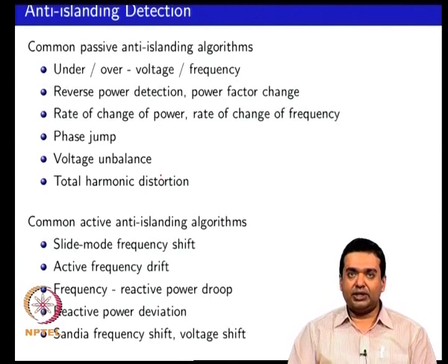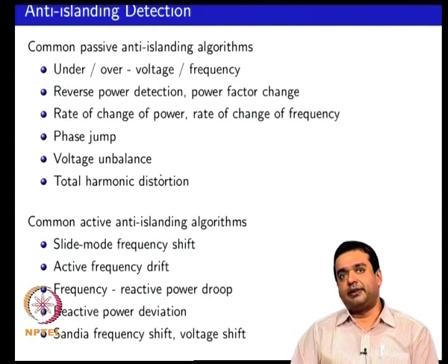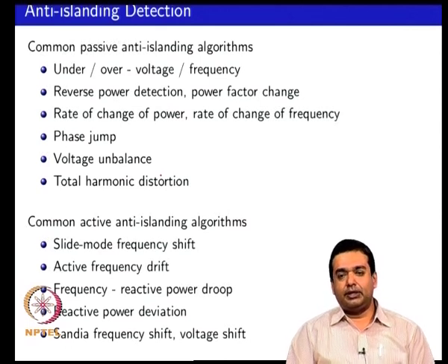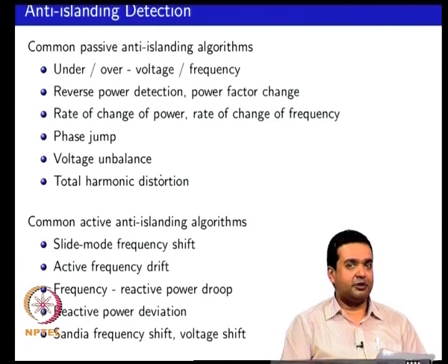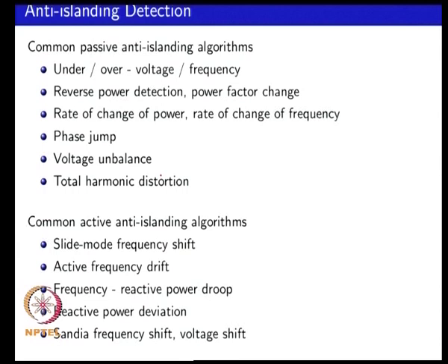People have looked at other methods such as power factor change, rate of change of power, rate of change of frequency, whether there is a sudden phase jump in your system, whether there is a large imbalance happening in terms of the voltage, whether there is an increase in THD that is being measured.